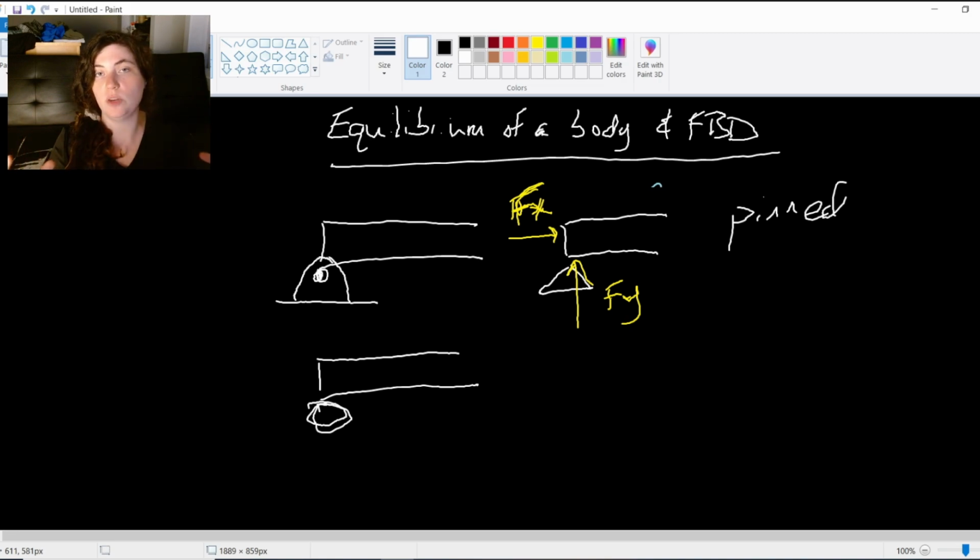And especially with loading, right? If there are a lot of cars on the bridge, then there's more compression happening on the concrete of the bridge. And if there are less cars, then there's a little less compression. So it needs this room to move around. Otherwise, our bridges would constantly be breaking because they're constantly under changing loads. So we have them on rollers. Some portions are fixed, some portions are pinned, some are on rollers, so that it allows this freedom of deformation.